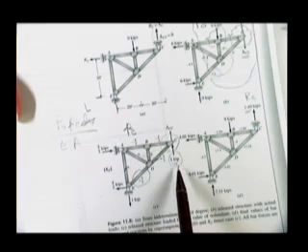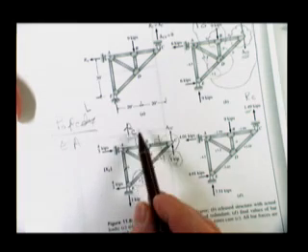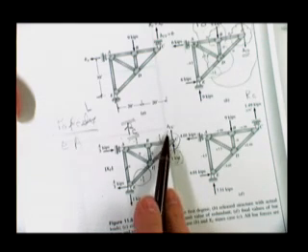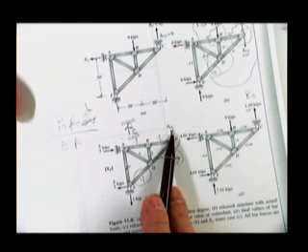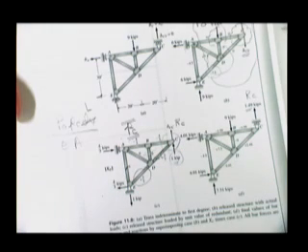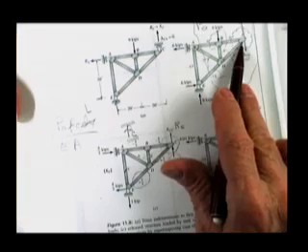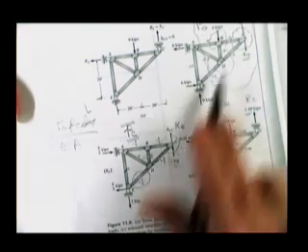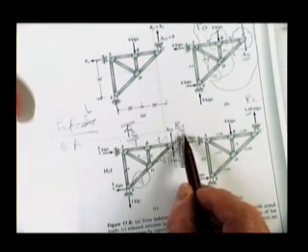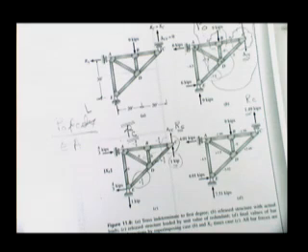That would be integral of this combined with this, and that would tell you how much deflection you're going to get at C due to a unit load at C, which you will come in and multiply by the reaction at C, and you'll set this deflection equal to that deflection, or this deflection minus this deflection is equal to 0, and you'll solve for the reaction at C. It's an identical procedure to the moments on beams. The only difference is, instead of being moments on beams, it's forces in axial members.